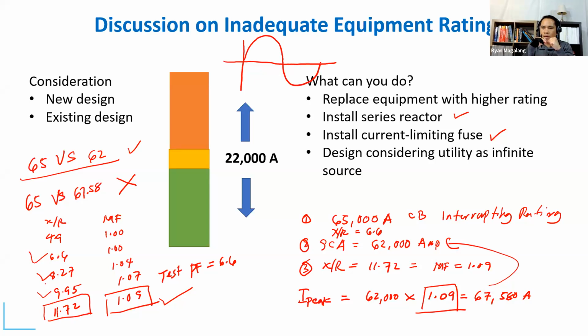When the metallic element melts due to the high magnitude of fault current, that material, I believe silica, gets exposed to that high magnitude of current. It crystallizes very fast, and it offers a very high value of impedance. And what that does is essentially choke the current.